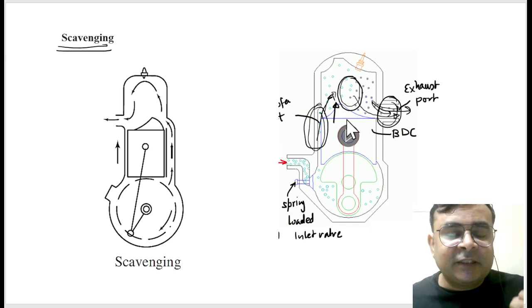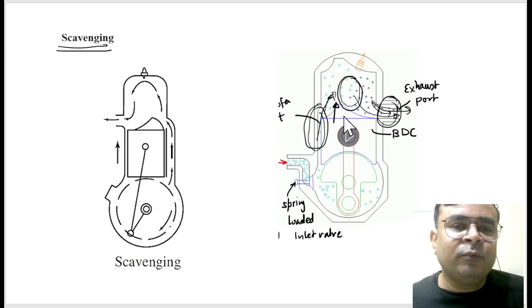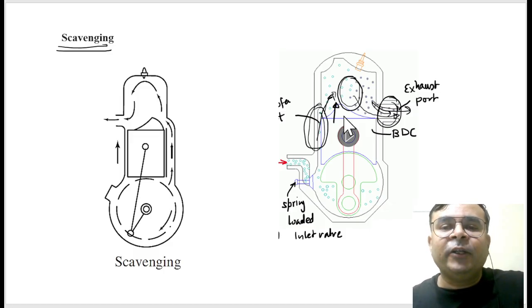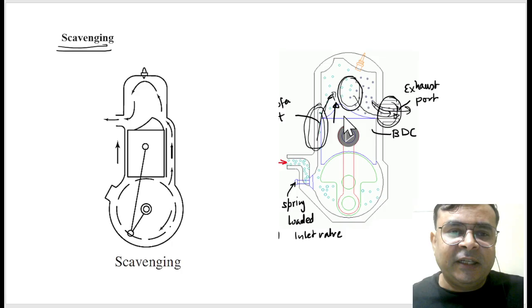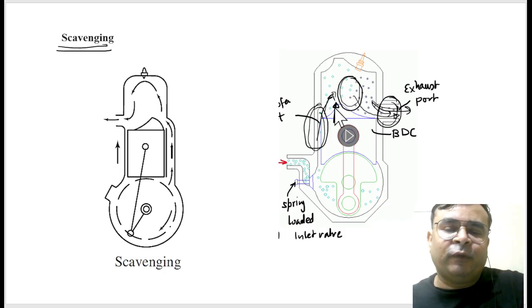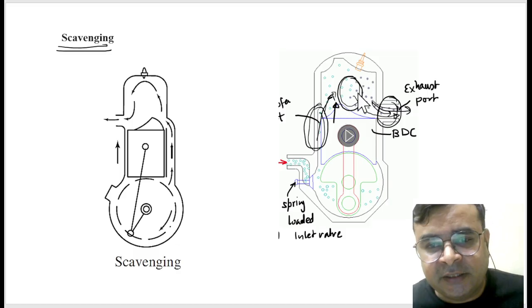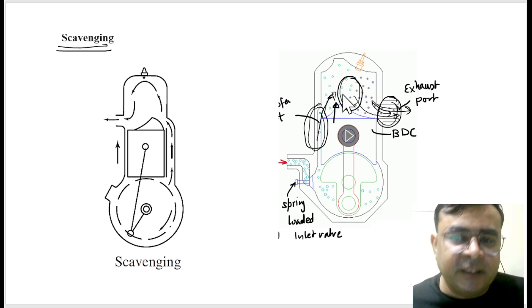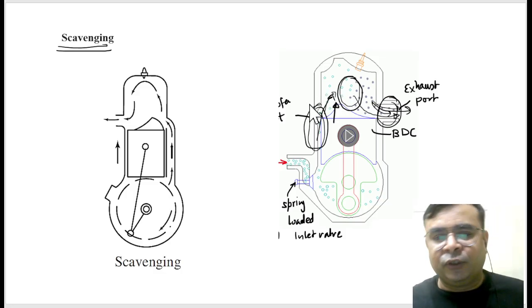Is it right? That's why in modern automobiles we always see four-stroke engines, because the entire fuel can be utilized for producing power. But in a two-stroke engine, fresh charge will also escape along with burnt charge. So here we have more wastage of fresh charge. That's why it gives us less mileage and less fuel economy. That's why these engines are obsolete nowadays. We have very limited application of two-stroke engines. Nowadays we are completely eliminating them and only using four-stroke engines.